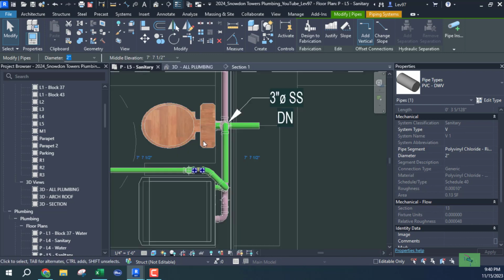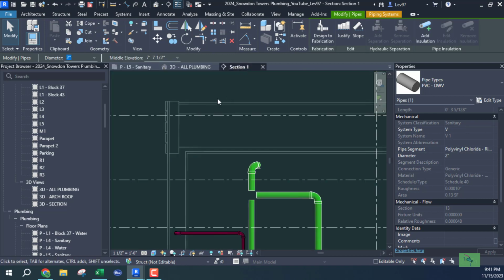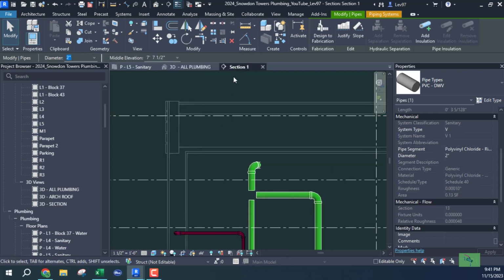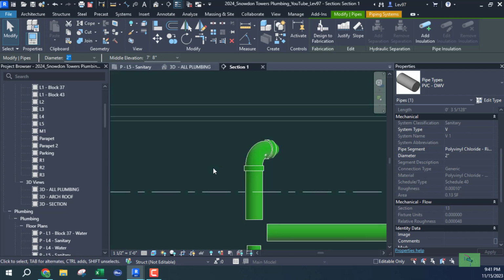And you're not going to go up and down in your plan view because there's no reference, right? But you can go up and down in your section view, although you can't see it. But if you select that pipe that's going to go up and down in the vertical plane, and you're in your section in your vertical plane, you know that you have a reference. So this pipe, as you can see, is going up and down. Your job at this point, I guess, is to guess how much you want to go up and down.